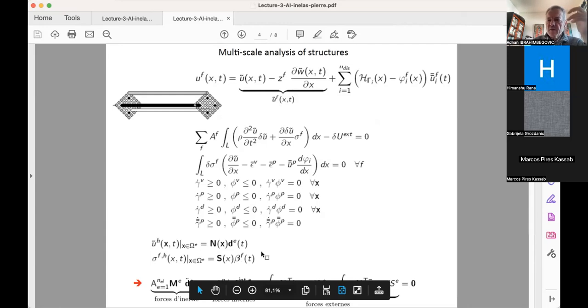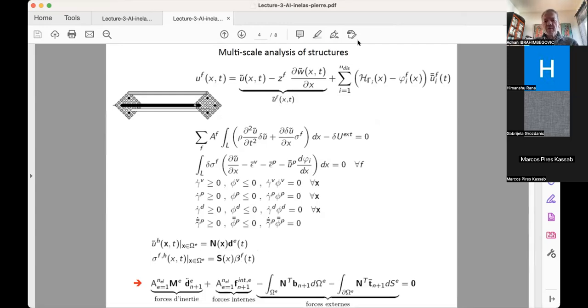If you have, for example, a two-node truss element, I can do that. Let me maybe illustrate that. That will be good for homework. I was giving you homework before to do this coupled damage plasticity, so why not try this? I have my bar, and a behavior where you have a yield stress, then a fracture stress. So this is sigma y, and this is sigma f, and this is some kind of value here where you can take both plasticity and so on.